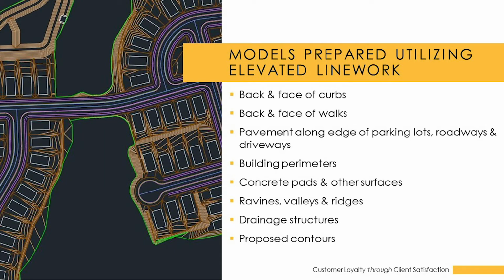Models are prepared utilizing elevated line work. So using the CAD file, we will prepare the surface model using a series of elevated 3D polylines. These are known as break lines or feature lines. The 3D polylines are created on separate layers to represent all hard surfaces such as curbs, walks, roadways, buildings, etc. These lines are placed and elevated per the information noted in the construction plans. Surface models are prepared using various CAD-based programs rather. All use the basic concepts such as 3D polylines or feature lines.